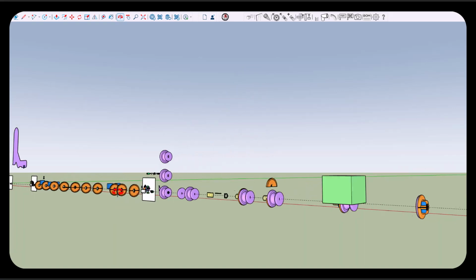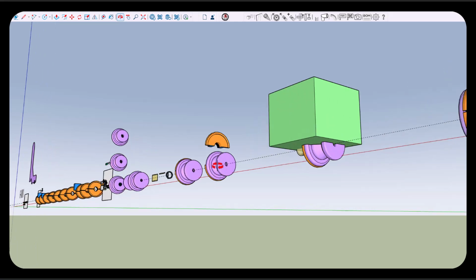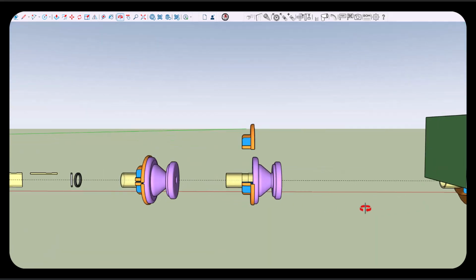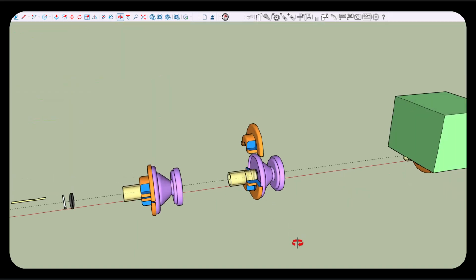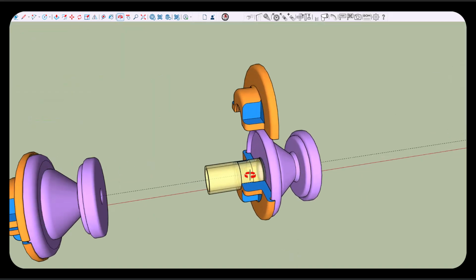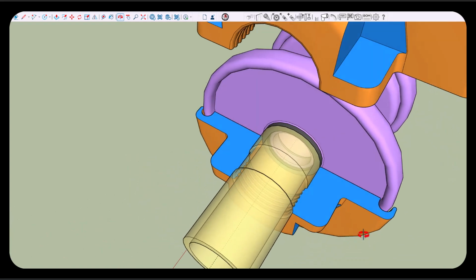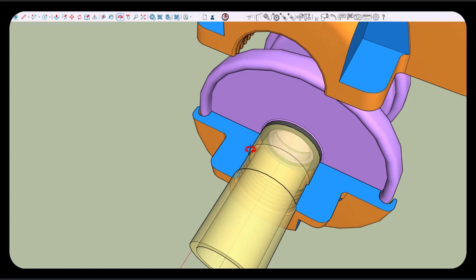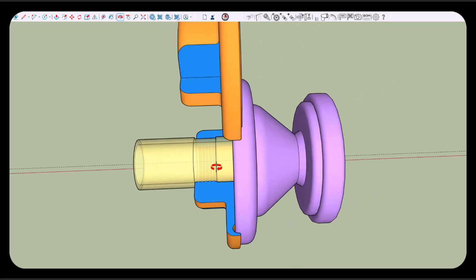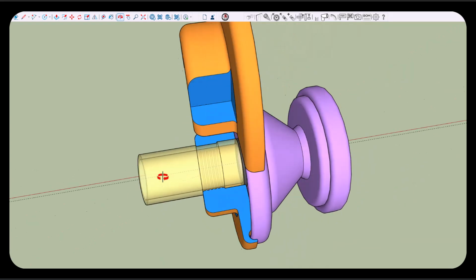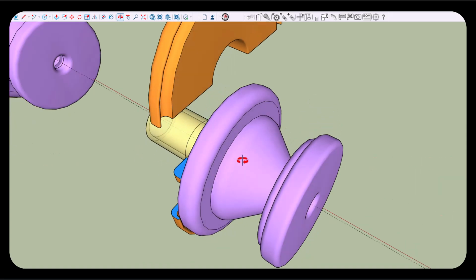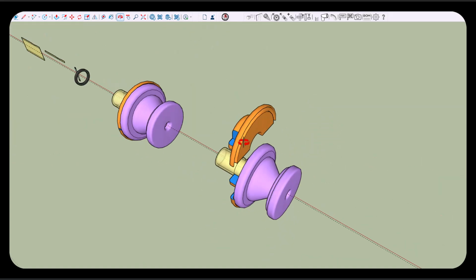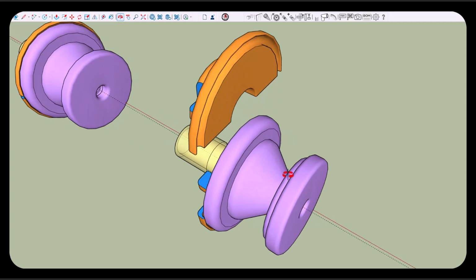So there's going to be 6 of those bolts there, and there's going to be another 6 bolts going around there, and that pulls the whole thing together, because I want to make this where I can put it together and take it apart, because I have a feeling that I'm going to spend my time trying to get this to work, and I need to be able to put it together and take it apart. And so I did a kind of a split view, and you can see the little grippers, and this is machined into it by your CNC machine. And so this is gripping this, and then this is going together, and then this is being held onto that by these bolts, and this cap is being held onto this by these bolts.